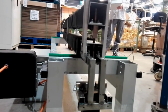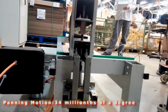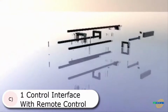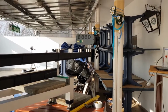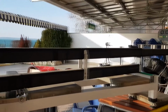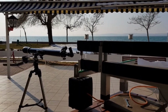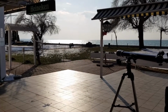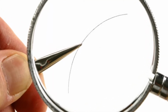The instrument had an accuracy of 54 millionths of a degree in the tilt angle and 34 millionths of a degree in its panning motion. This was accomplished with two high-tech stepper motors capable of making movements as small as 1/10,000th of a rotation. That is equal to 36 thousandths of a degree. This rotation movement was transferred to a bolt with fine threads 1.5 millimeters apart. That meant the rail where the laser was attached could be moved in steps of 15 hundredths of a micron. That is less than 1/1000th the thickness of the thinnest human hair.